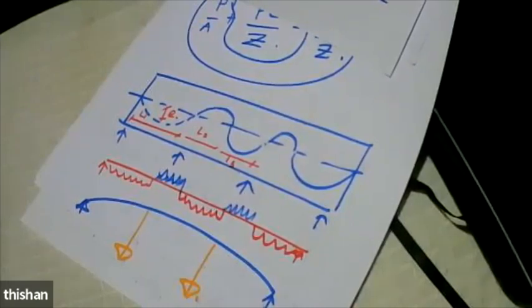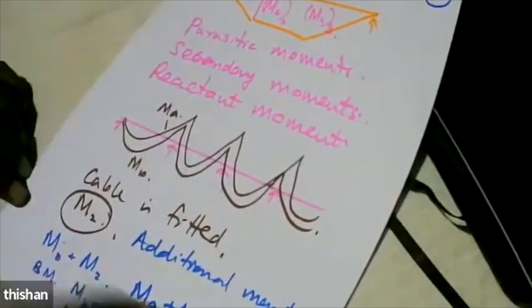And because of that, the beam will be lifted up. But in practice, beams cannot lift up like that. So because we are not allowing the beam to lift up, there will be forces acting downwards. And these forces will give rise to a sagging moment diagram, right? And so you get a bending moment diagram like this.